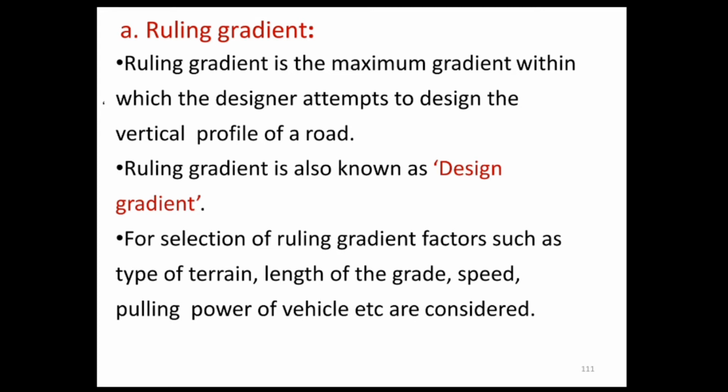The selection of the ruling gradient for the purpose of design is a complex job, as several factors such as the terrain, length of the grade, the speed, the pulling power of the vehicle, and curves are considered. In hilly roads, it may not be economical or sometimes not even possible to adopt the same gradient because of the large difference in levels to be covered in a shorter length of the road.